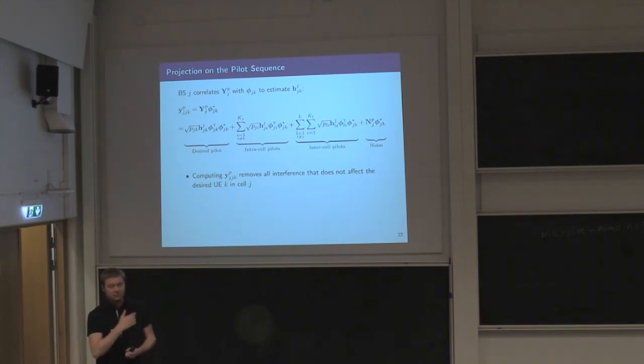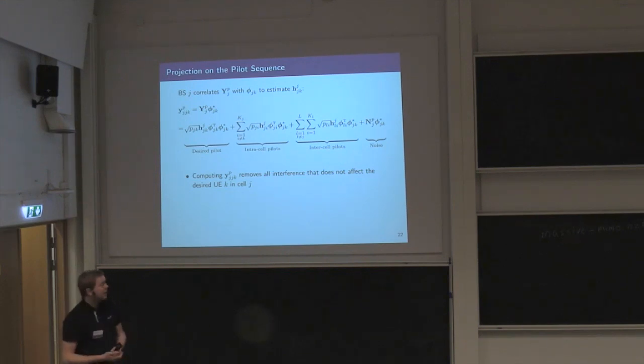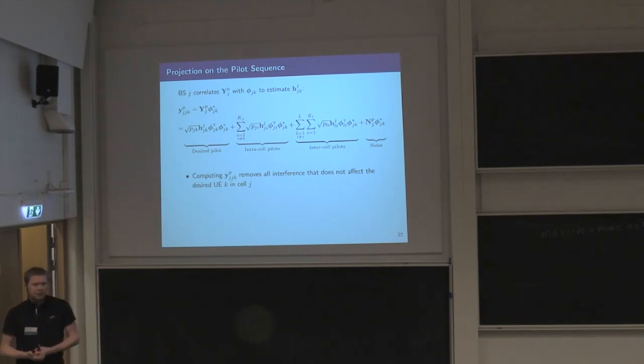So in multi-carrier system, do you apply the same sequence for the subcarriers? You can have the same sequence on all subcarriers for the reason that we assume that the statistics are the same in each of these coherence blocks.